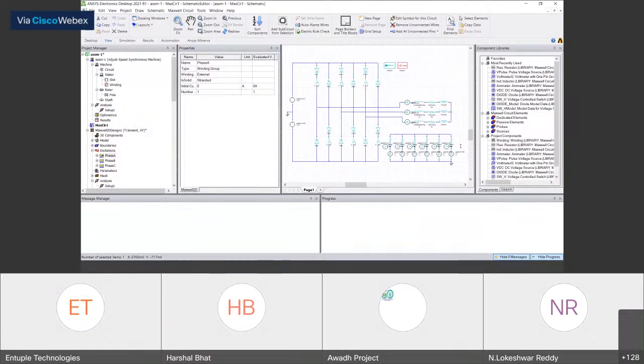You can also define the insulation conductivity as a function of that electric stress. If the breakdown is causing an increase in conductivity, you can put the conductivity as a function of electric stress. That means after a particular electric stress, the resistance will just drop and current will start flowing. That kind of thing can be done, but breakdown as a concept is a chemical process, and the chemical process cannot be done in Maxwell. You can look at it in a different way and get the desired quantity out.